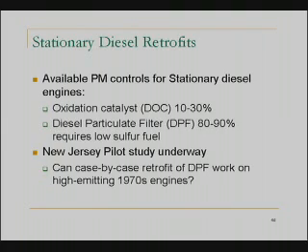Typically, diesel particulate filters have only been applied to relatively recent model years of diesel engines, and oxidation catalysts can go back a few more years than DPFs. But generally, the verification process and the verified technologies are looking from roughly the mid-90s on.